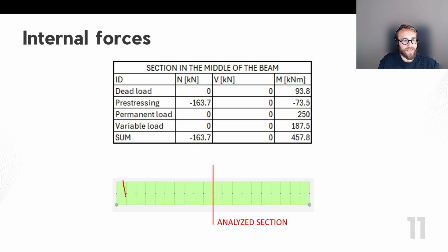So this is, for example, the area very close to the support, where if you make a strut and tie, you will receive the proper behavior and the code check. But if we analyze the area in the middle, where there is a zero level of shear forces and it's very far from the boundary condition, not a discontinuity region, we can assume that the linear plane of strain is guaranteed, so we can analyze and compare those two solutions.